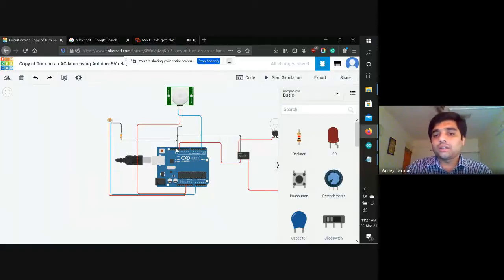In the diagram, if you can see, there is only one relay, but we are having 8 relays, or we are having 4 relays. So the entire board will have a common ground port. There will be only one ground, and only one VCC port. The VCC port will go to 5 volt, and the ground port will go to any ground of the Uno. Then each relay pin will be triggered with each digital pin out of that Uno.